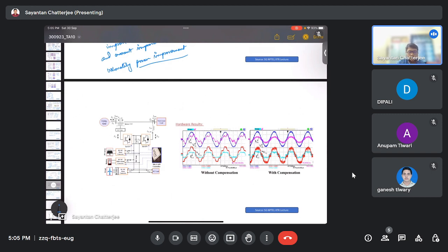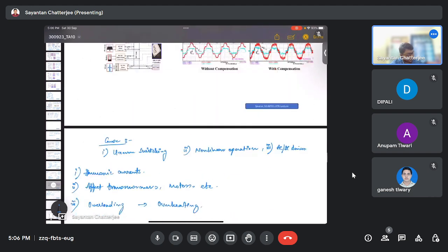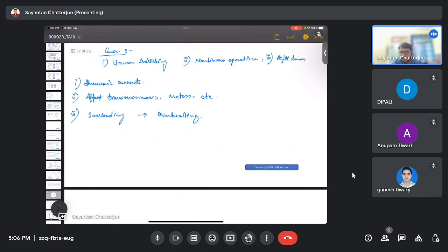Because now in the microgrid system, if we have system harmonics in place, then the regular operation of the devices, which are designed to work on the fundamental frequency, would face some issues imposed on those equipments, like overloading and harmonic currents injection.